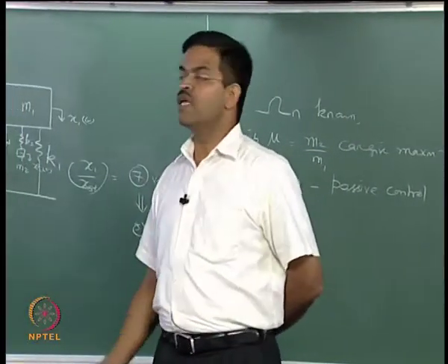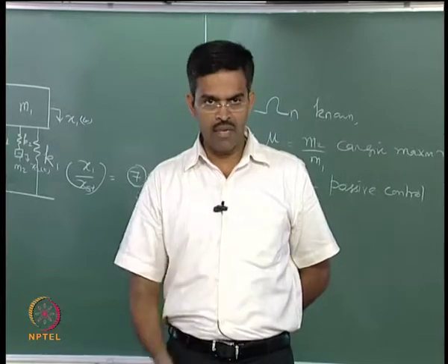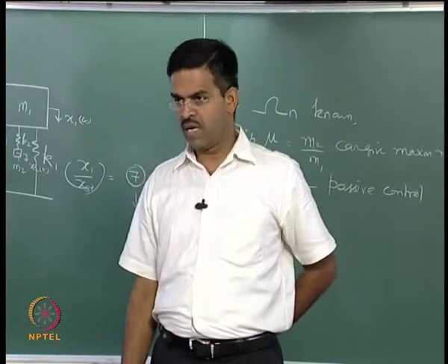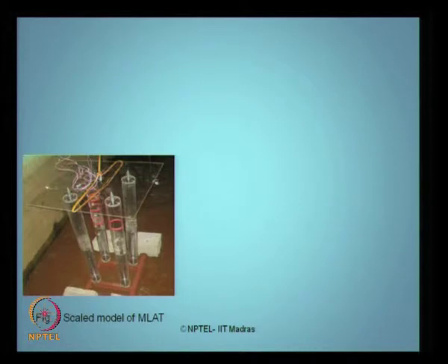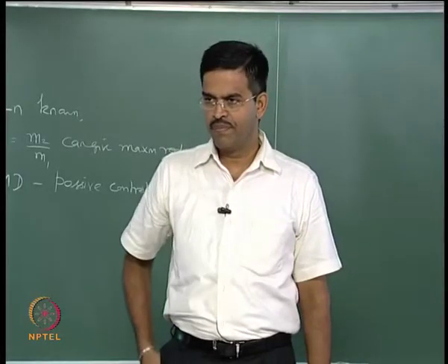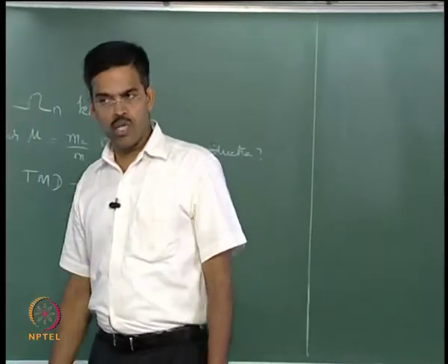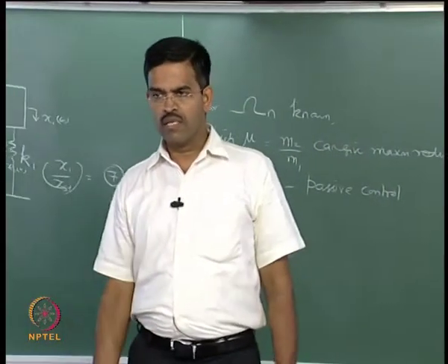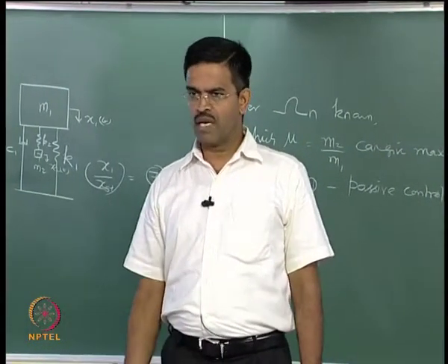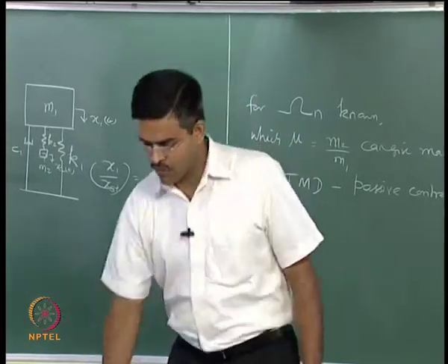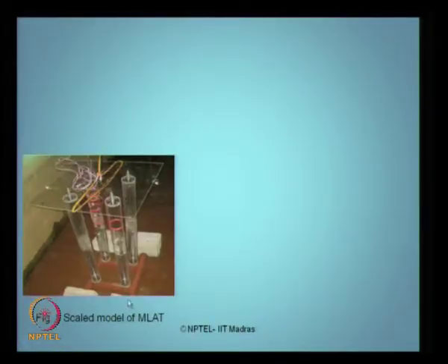By providing an additional hinge at the connectivity between the tower and the deck, you can reduce the response of the rigid connection. And of course, you will realize now that when I am providing the top hinge, this particular point has no wave action at all, because it is very much above the mean sea level. So, there is no wave action here. This will not get corroded, because it is very much away from the clear head sea condition of the wave, from the upper tide level or high tide levels. The bottom one of course is a functional characteristic, a structural configuration which is already present in the single leg towers also, that is nothing but a structural hinge.